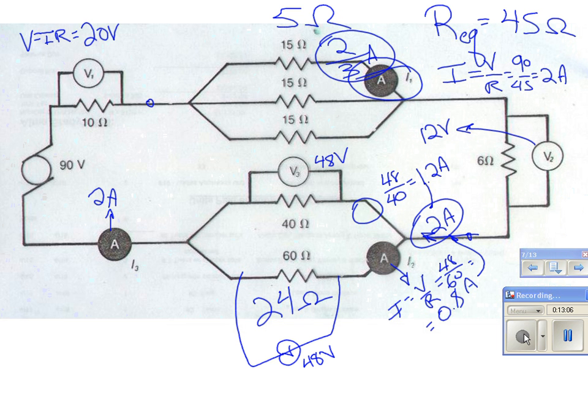But let's go the other way just for fun and see what happens. We know that this is 5 volts, right? So if I wanted to find the current through this path, I equals V over R. I'm sorry, 5 ohms, 10 volts. Thank you. So this section uses 10 volts, right? So if I did 10 volts over 15 ohms in this path, I would get 2/3 also. I get the same answer. We hadn't done it yet, but this whole thing is like a 5 ohm resistor, and the total current is 2 amps, so that would be 10 volts.